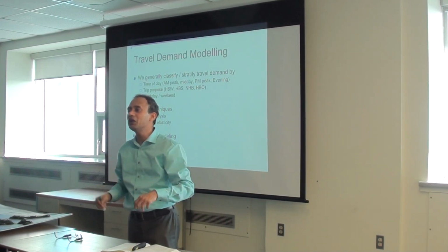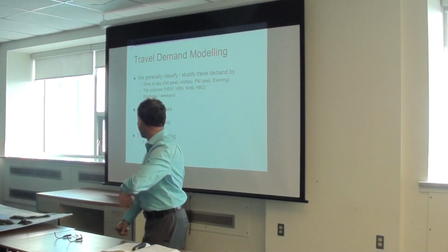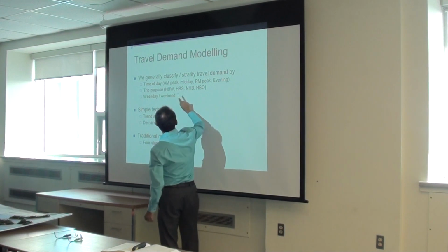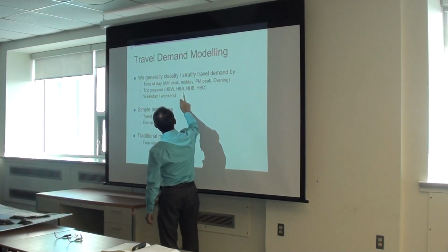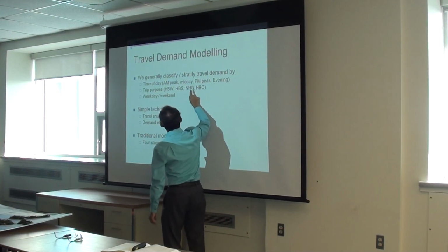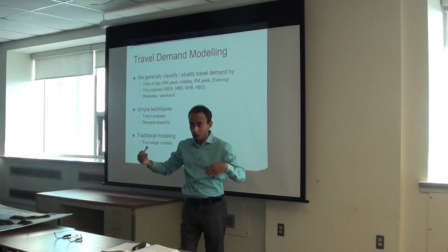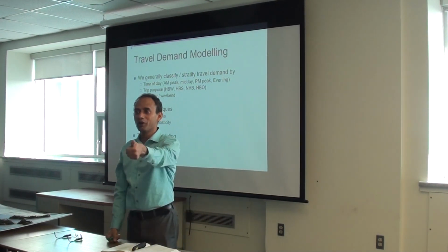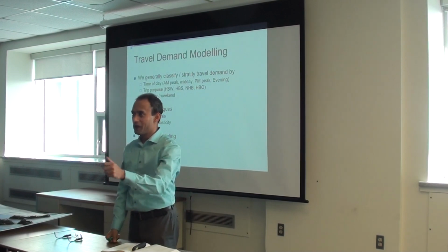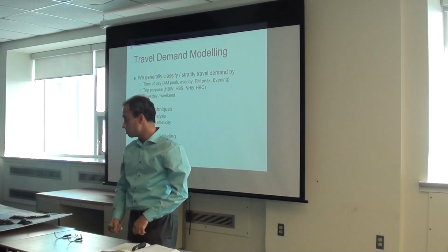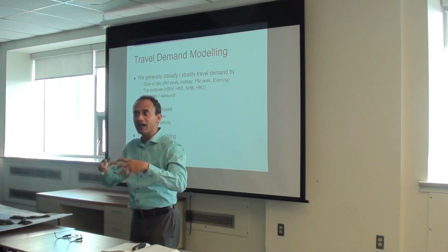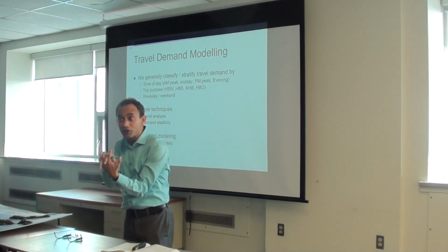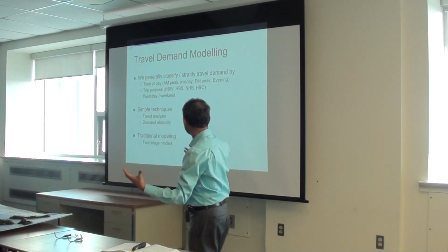And for a simpler model, we just do work trip and non-work trip. Means home-based work, and this is the commute trip, home-based school, and home-based others, and this is non-home-based others. Non-home-based means, like, from school you are going for grocery shopping, recreation, or a yoga practice. So we lump all of those together in one trip category, because those are important trips too.